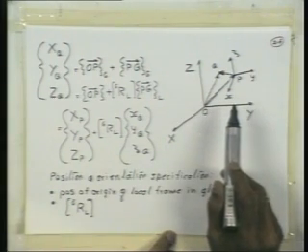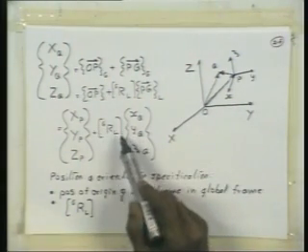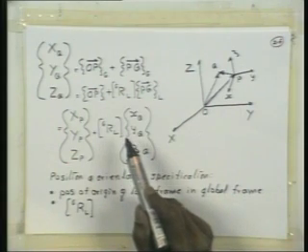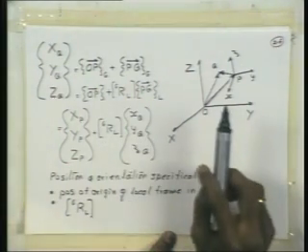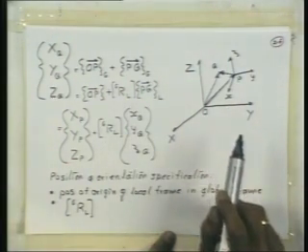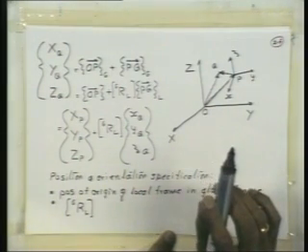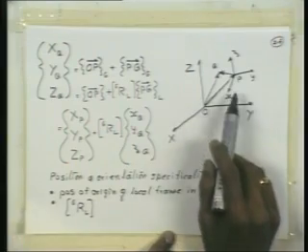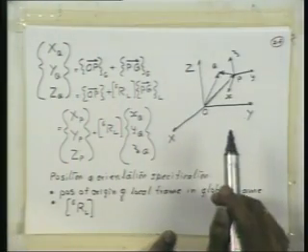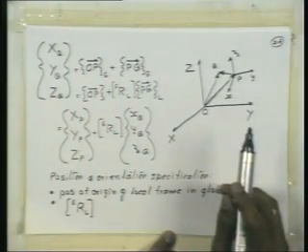The three unit vectors put together as a matrix because that is convenient for transformation. These four vectors, which make up 12 parameters, form the position and orientation of this rigid body with respect to this. That is how we specify that.